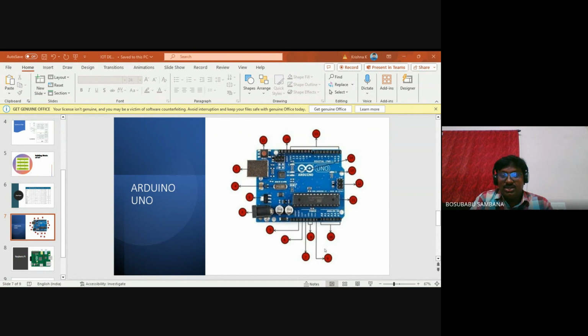If you are using an Arduino Diecimila, the board must be set up so that it receives power from the USB cable. A jumper, a thin plastic piece that slides onto two of the three pins between the USB and power jacks, is used to switch between the two power sources. It should be on the two pins that are closest to the USB port, so check those. The Arduino board can communicate with the computer via a USB cable. The PWR indicator light, which is green, must be on.